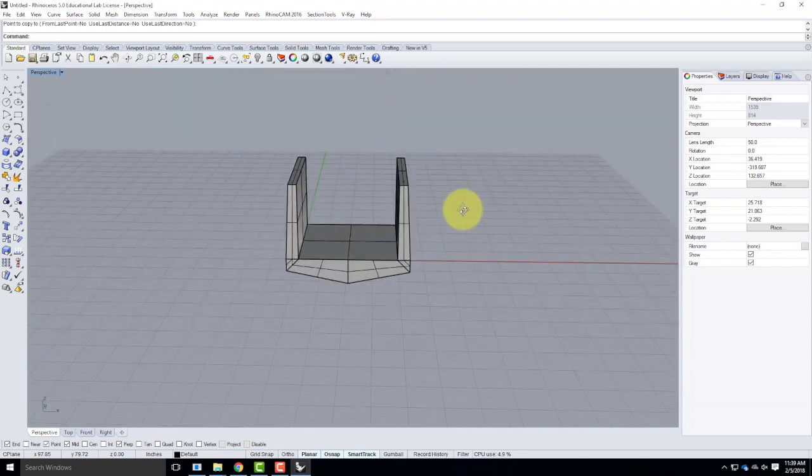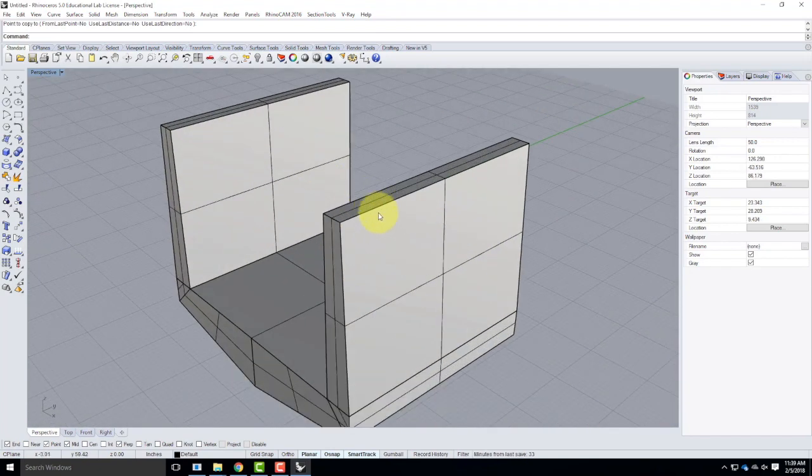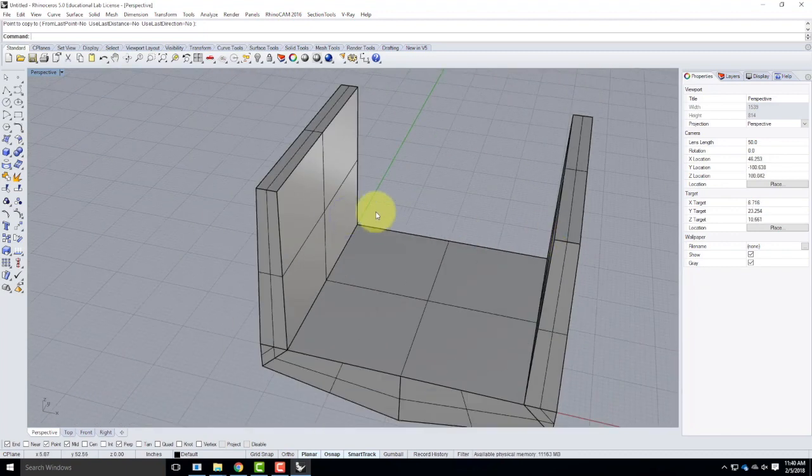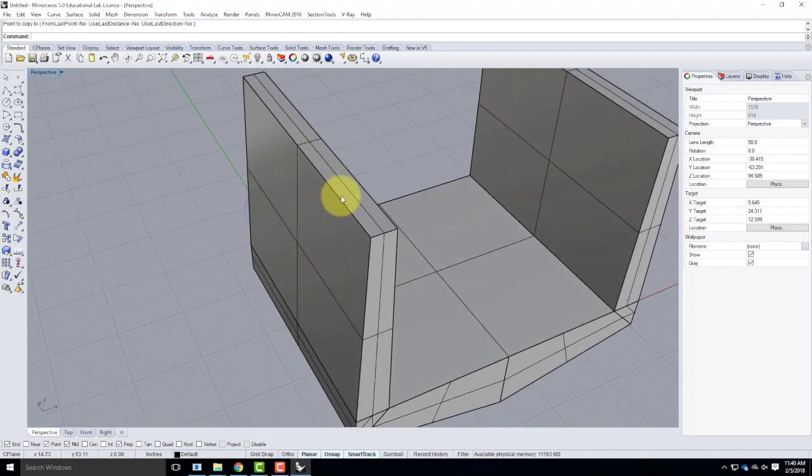Okay, so now that I get to this piece, it's now time to start beveling the corners. This is a little piece of a concrete bridge, a walkway. And we're going to bevel the corners so that if we were actually doing this in real life, we wouldn't have 90-degree corners that would cause breakouts when you took the forms off. But that's a construction thing, not a practice thing. Anyway, we're going to go ahead and bevel these corners. So I'll start right over here with this side.